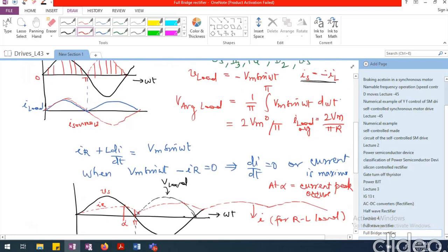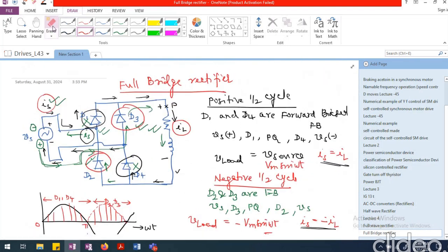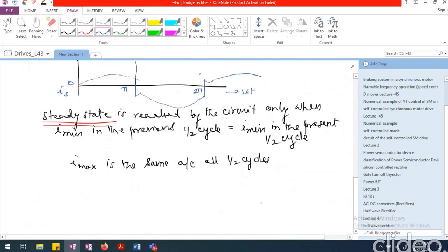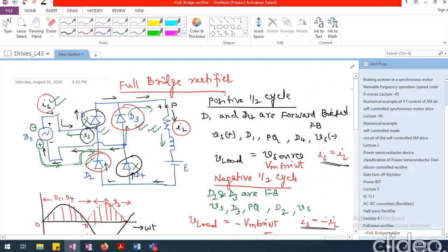One more thing I would like to analyze is if we have an RL load, that is, if I am going to have R, then inductance and a battery. If I'm looking at a battery charging circuit, where a battery is also connected, it is as good as looking at whether this battery plays a vital role in deciding whether this diode is forward biased at all or not.